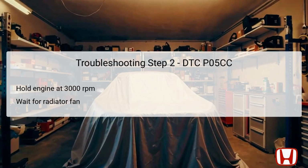Next, hold the engine speed at 3,000 RPM without load until the radiator fan activates. This procedure allows the engine to reach an operational state where the VTC system can effectively regulate intake camshaft timing. Maintaining this RPM is necessary because it triggers the conditions under which the VTC system operates under normal circumstances.